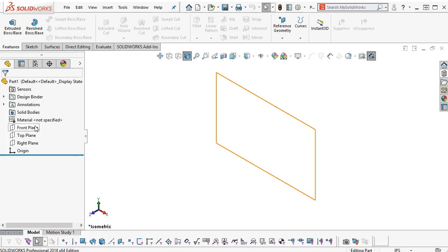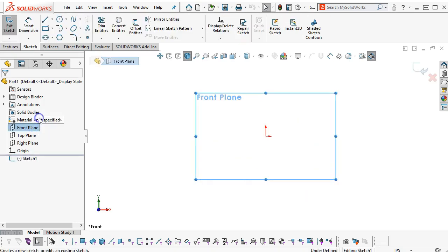So when I pick a plane, the front plane, and we open up a sketch, then in the options we've pretty much told it that we want this to go normal to that sketch when we open it up. It doesn't necessarily have to, but when we do the option settings later on, we can turn that off and it will stay in whatever visual orientation we started with.